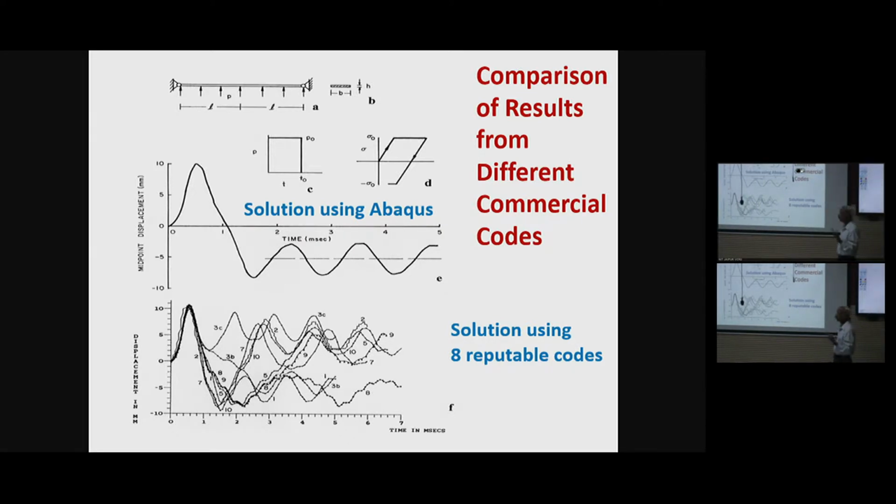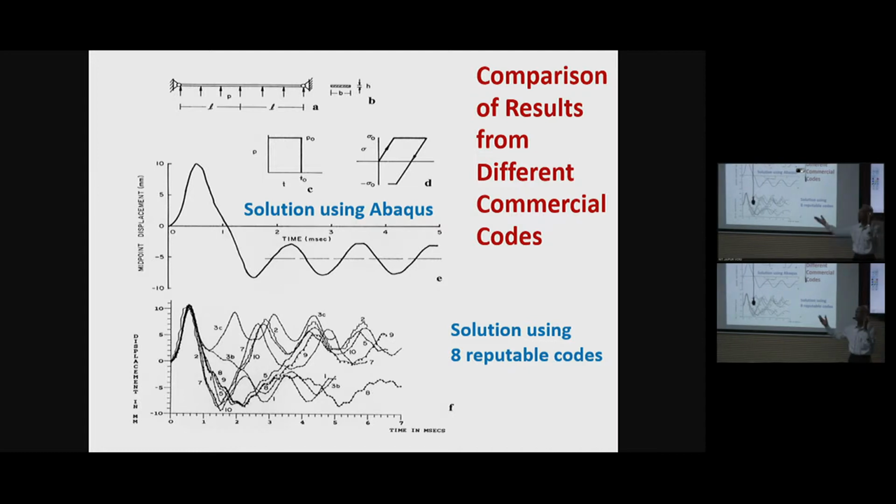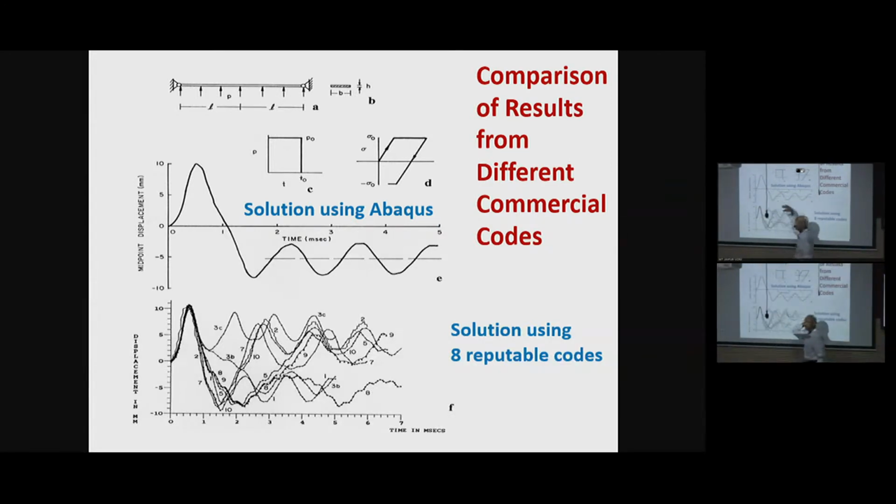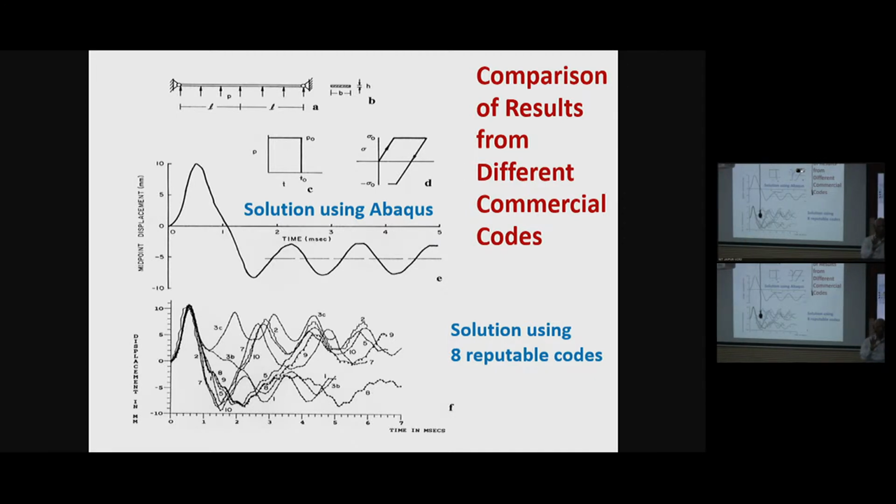Number one. Number two, I think many of you asked me when I was doing the beam problem why the load is acting up, but we were doing a linear elastic problem, so it was deflecting up. But this one is an elastic plastic problem. The normal expectation will be that the center of the plate will move up. But as you can see, it moves up and then it stays below the undeformed state. So it's negative. It's the reciprocal or inverse of what we intuitively expect.